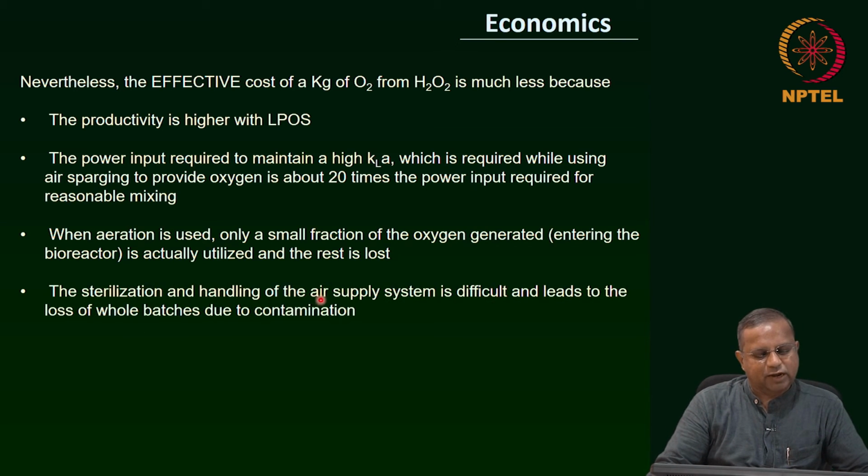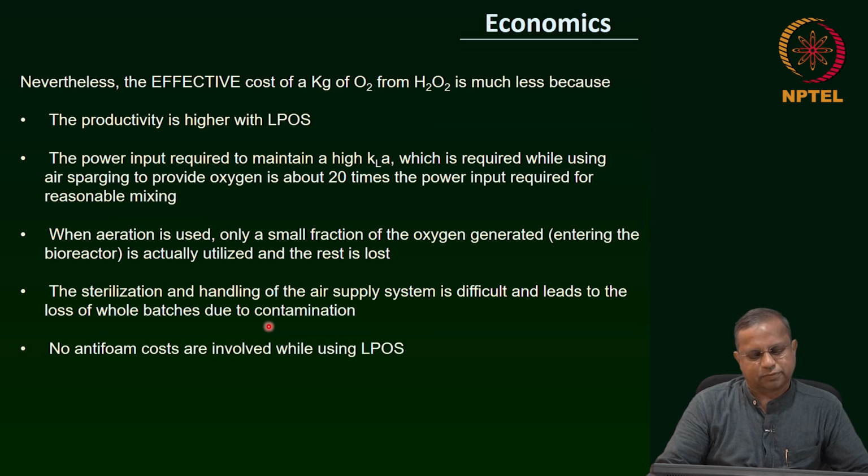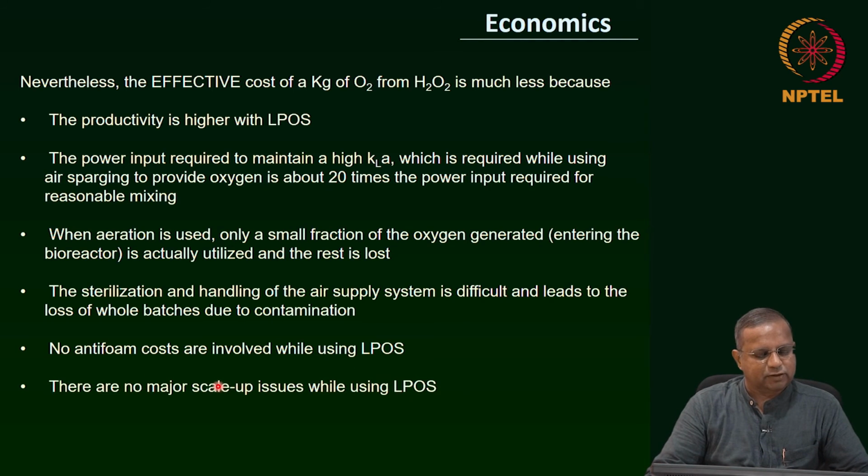The sterilization and handling of the air supply system is difficult and leads to loss of whole batches due to contamination. This is also a problem. There are no antifoam costs involved while using LPOs. There is no foaming, therefore, no antifoam needs to be added. And there are no major scale up issues while using LPOs, because mixing is the only factor. You are not worried about KLA and so on, which are a lot more complex to scale up. LPOs, mixing is quite easy to scale up comparatively.